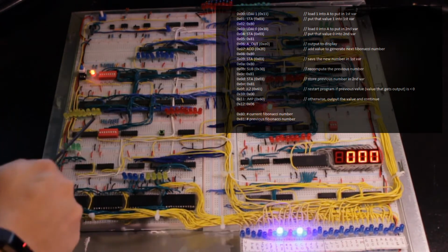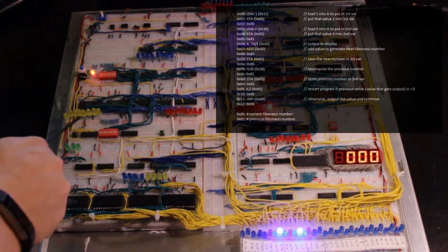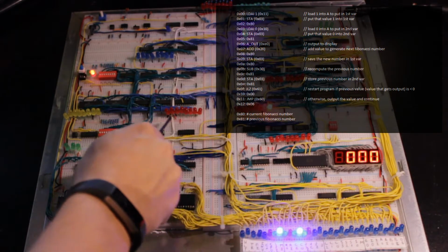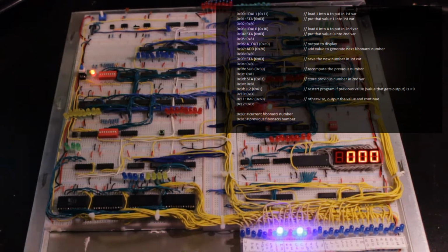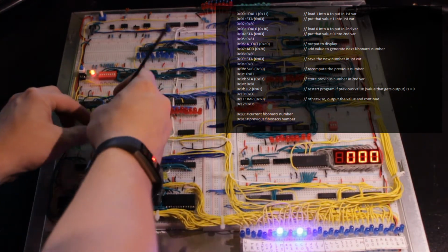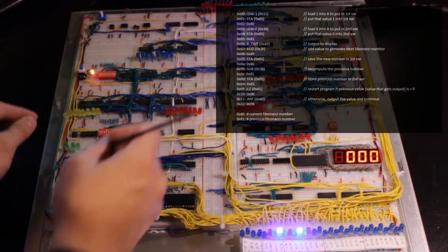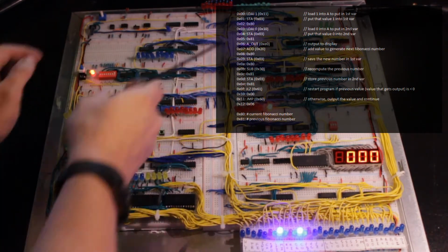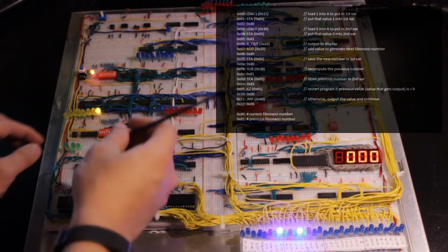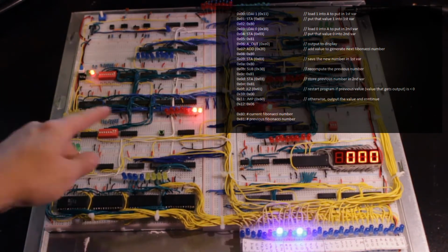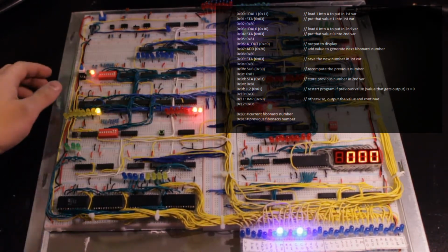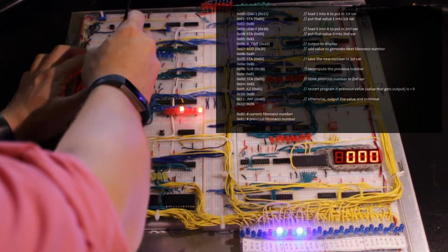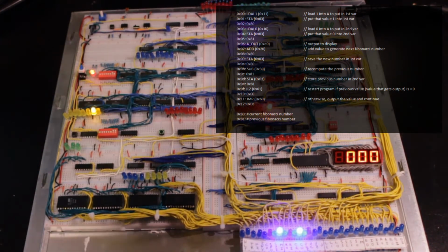So first, in the 0 position, which we can see we're in address 0 on the yellow address register readout here, and then we can see we have a value of 0. We need to put a hex 11 for load A register immediate with a value of 1. So we put in here hex 11 and we press the right button, and that goes in the first index in memory. Then next, in memory index 1, we're going to need to put a store A command, which is hex 03. So we input 0 and then 3, binary on the second 4, and the memory index after that, memory index 2, is a pointer to the location where we're going to store that value.